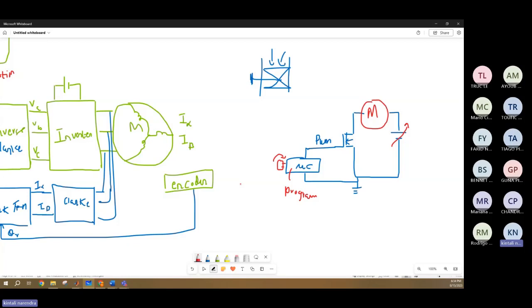So I need to increase the speed or the RPM to maintain the same speed. So the same thing here, everything is the same logic. Any microcontroller is the same. You program it to control the switching of your MOSFET, which in turn tells you how much current the motor should get to rotate.